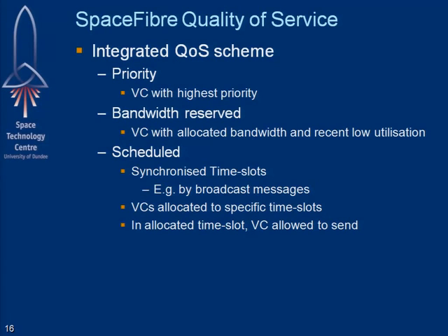Scheduling: we chop time up into a series of time slots, which are synchronized, for example, by broadcast messages or local time. And the virtual channels are allocated to specific time slots. In an allocated time slot, a particular virtual channel or group of virtual channels are then allowed to send information.